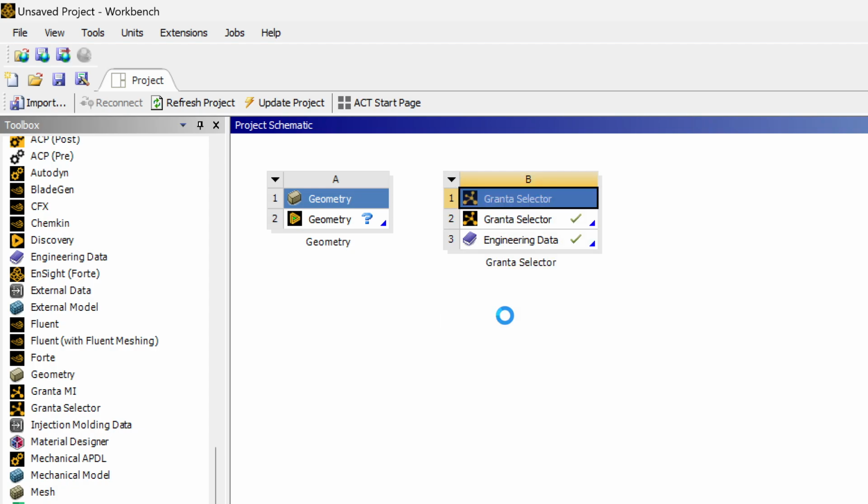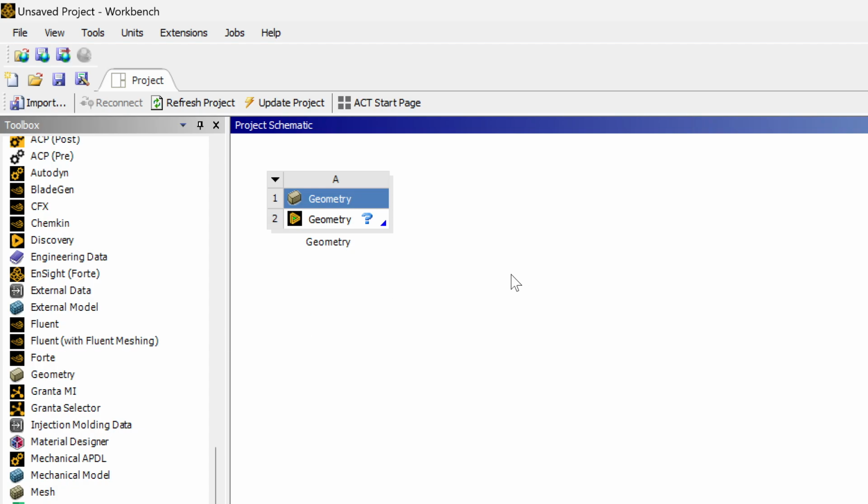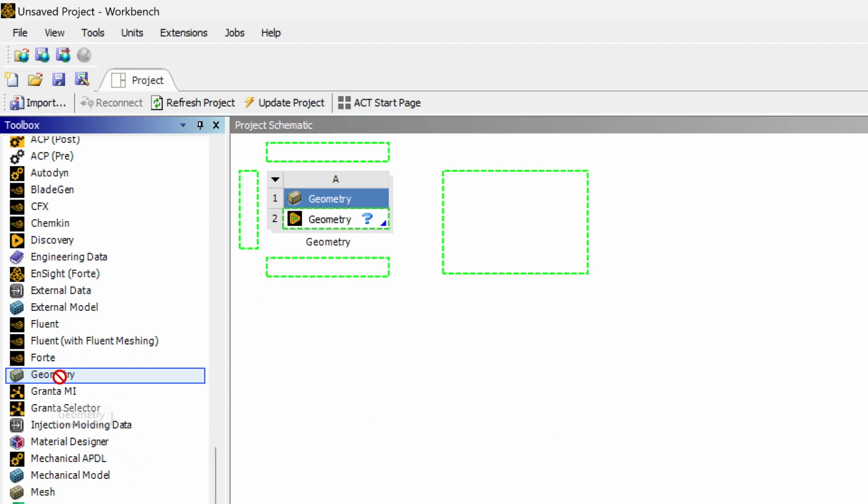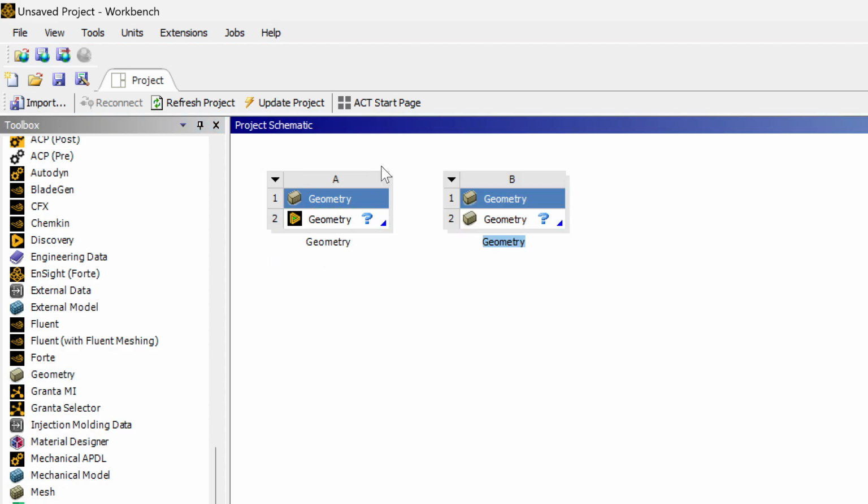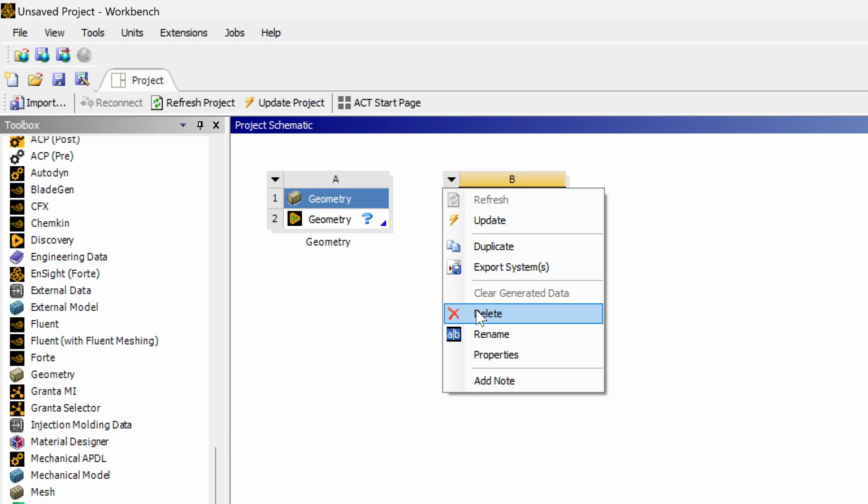Our focus today is on the geometry. So we want to start by building a geometry. And the geometry we want to build today is just a traffic light beam, and we want to put this in a box and essentially put it through wind and see how the structure reacts, how the fluid movement is around the support mechanism that we have. Okay, so for this you just have to drag and drop the geometry. I've already done this, so I'm just going to delete the second one.